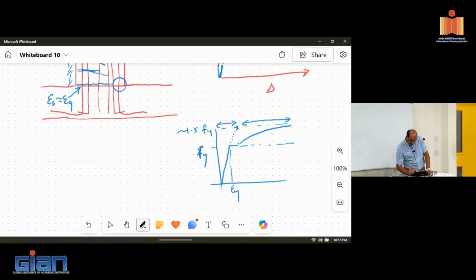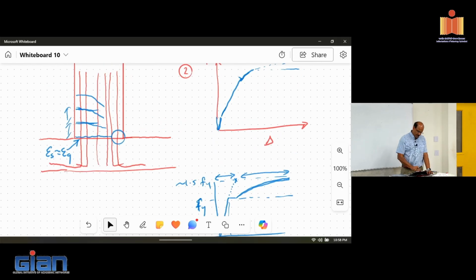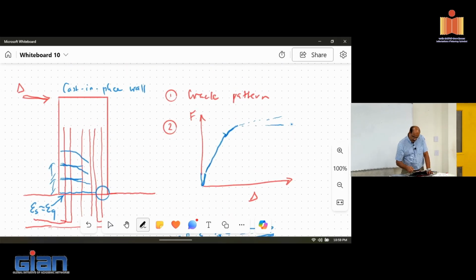So this increase, if the rebar carries, most of the rebar actually have the strain hardening behavior. There are some, I think it's called Tempcore steel in Europe. For some reason they produce them without strain hardening, which tend to be more flatter than what you see. There's advantage actually having, so the actual behavior, if no failure takes place, will follow a path like that, and then somewhere it's going to fail.